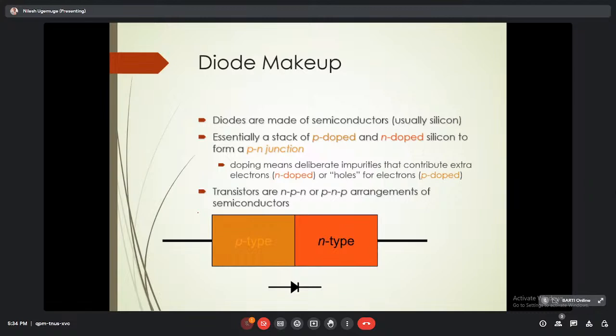So this is not the way that you connect a p type material and an n type material separately, it will not work like that. If we are taking p type material, then we are growing the n type layer into the same material. Then and only then can a PN junction be formed. Otherwise, the diode cannot work. So in that way, we have to see the PN junction diode.